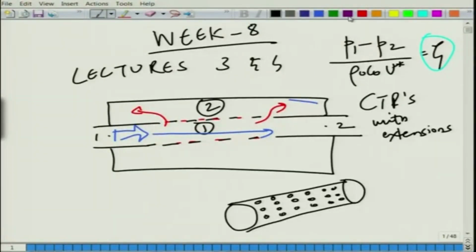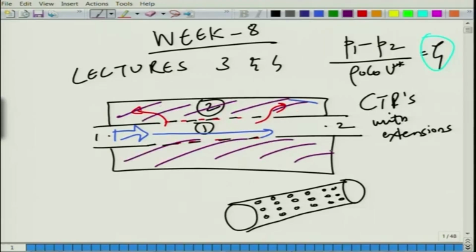If this area is filled with an absorbent material like rock wool or glass wool, then of course quite complicated expressions for the impedance of the perforate exist. So, here we consider bulk reaction. Maybe if we get time, we will consider this in the course. Here, in the bulk reaction models, there is regular wave propagation in the airway. But before the wave goes into this material, it has to cross through the impedance of the perforated bridge. So, for that we need to develop suitable expressions. People have already done it.